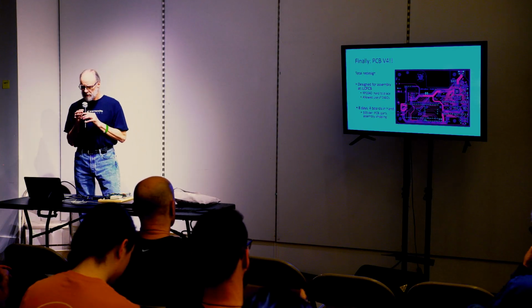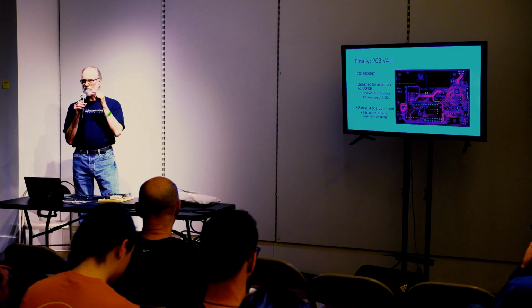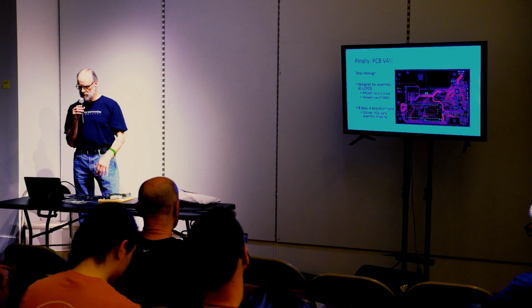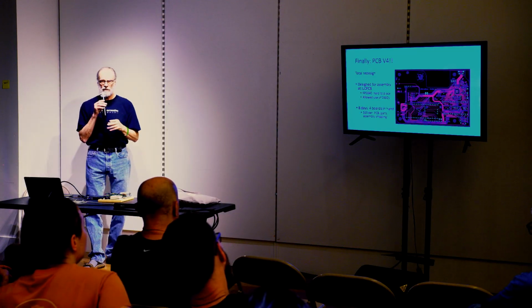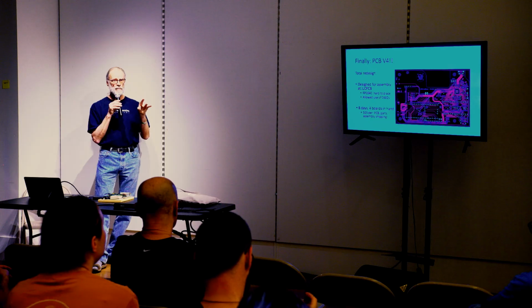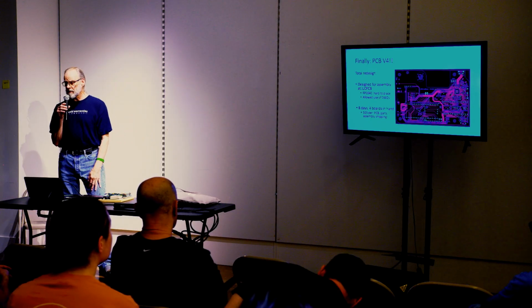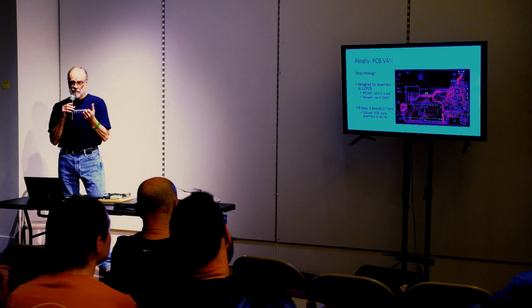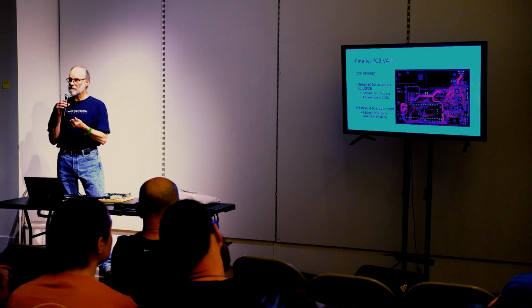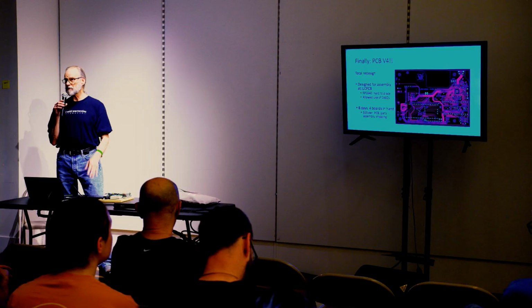Because the RP2040 was so teeny tiny and my eyes are getting older, I decided to have this built at JLCPCB and have them do the assembly as well. And that was a really good decision. It worked really well. It let me use 0402 parts everywhere instead of 0603s because I was not going to be hand soldering them.